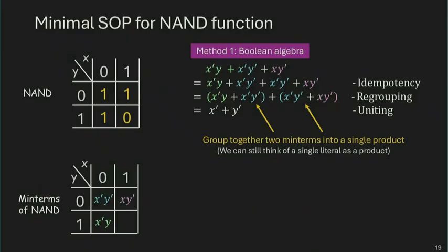All right. So again, let's start from some of the basics. Try it out for a NAND circuit. That is the truth table for NAND. 0, 0, 0, 1, 1, 0, produce an output of 1. If we want to represent it as a two-level circuit, using an OR gate preceded by some AND gates, what you can do is represent it as a sum of min terms. That is a canonical representation, the unique and complete method to represent any Boolean function.